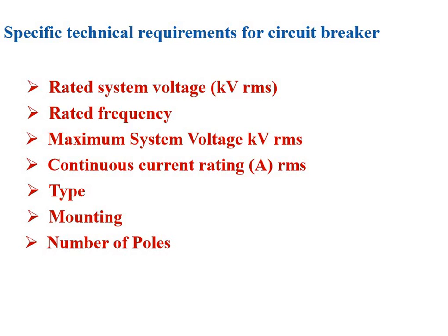Single pole circuit breakers are available, 2 pole circuit breakers are there, 3 pole circuit breakers are there, 4 pole circuit breakers are there. So depending on your requirement, depending on your system, or depending on your convenience also, instead of using a single circuit breaker of 4 poles for a 3-phase 4-wire system, you can go for 4 single pole circuit breakers for a 3-phase 4-wire system. So that is the choice of the system or choice of the design engineer.